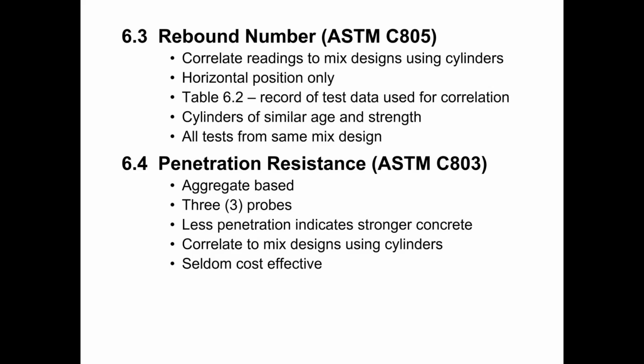And so for that reason, if you are going to use a rebound hammer on a regular basis at a plant, then you need to do correlation testing so that you develop data and a correlation curve that is specific to the mix design or mix designs that you're going to have in use at your plant.